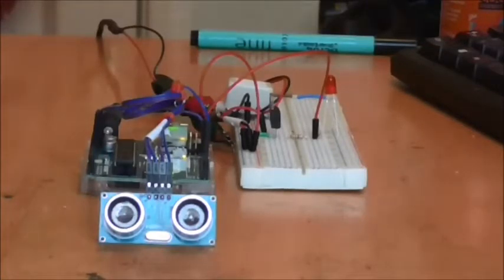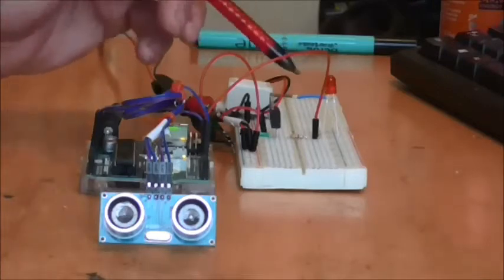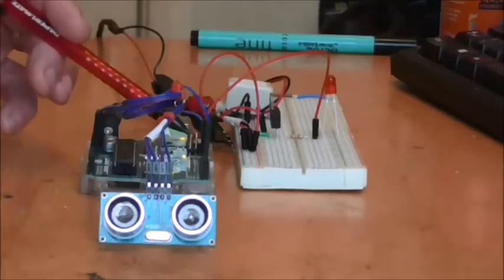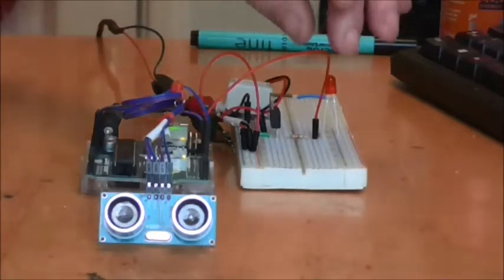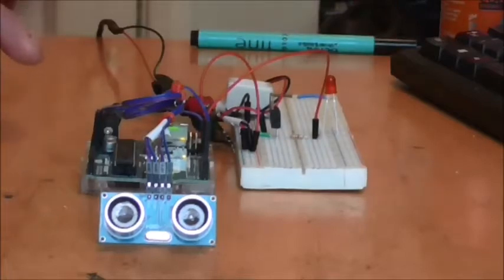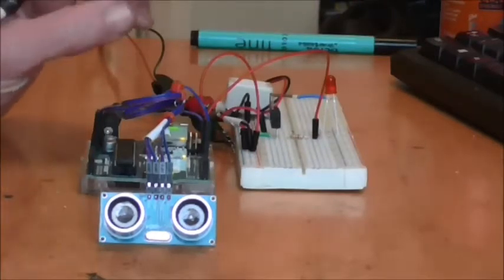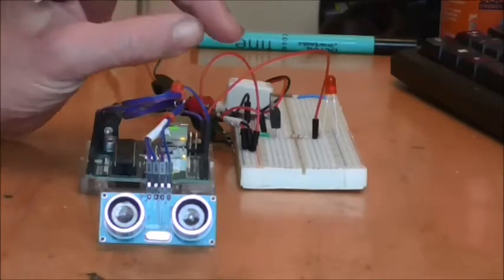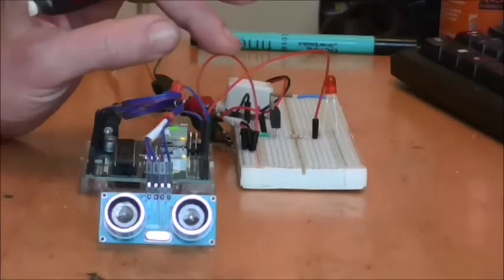We have the Arduino attached to the base of the transistor, and at the other end, pin 7 of the Arduino is attached to this wire here. Something I didn't show on the drawing, but which the Arduino really needs if it's to work with this circuit, is a common ground. So there is a common ground between the Arduino and the breadboard there.